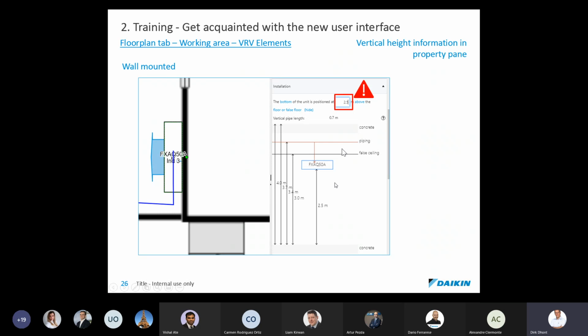You can only define heights on floor level, and on the indoor units that are deviating from that, you will have to play around with this setting. So there is no other way. I know some of the buildings can be complicated with mezzanines or big halls that go across several floors. In this particular example, you will have to be a bit flexible and find your way in it. But for sure, I think most of the cases you will be able to tackle.